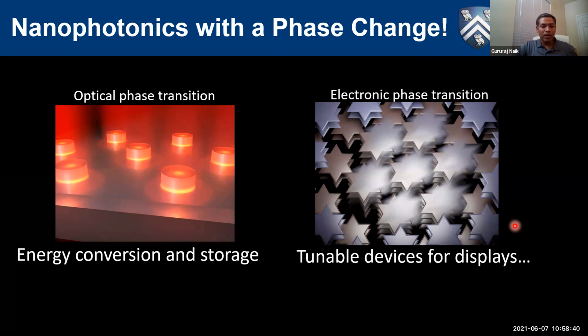But how do you couple light more into this vertical axis? Exactly for that reason we use the plasmonic gratings. We could have used even dielectric gratings, but when you have plasmon resonances like metal, you always have very strong vertical fields, right? Your polarization is in-plane, you have strong out-of-plane fields, and that's why we see this tunability enhanced. So there are two components to the device. One is choosing a material that has a huge tunable response, which is the first part. The second is building great antennas that can couple the tunability of this material into a far-field functionality.